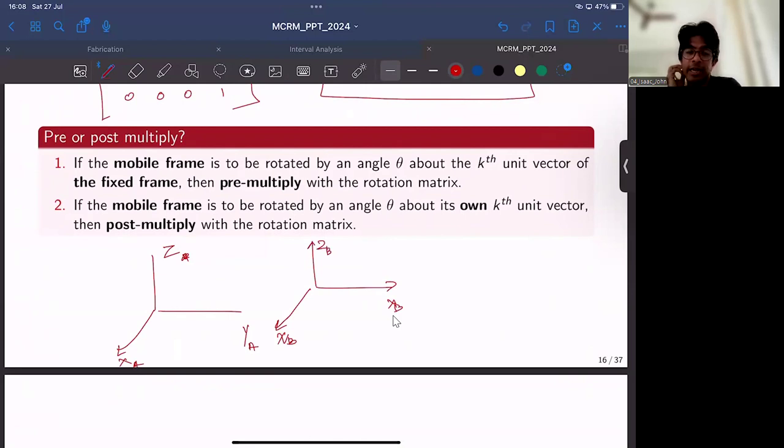So rotations actually can happen in two ways. Either you can always represent the rotation with respect to the fixed frame of reference. So if you consider frame A to be fixed to the ground, you can realize any arbitrary orientation for frame B using successive rotations about axes xa, ya, or za, which are the axes of the fixed frame. So either you can manipulate B using fixed rotations along xa, ya, and za. That is one way. Or you can rotate about the current frame of B.